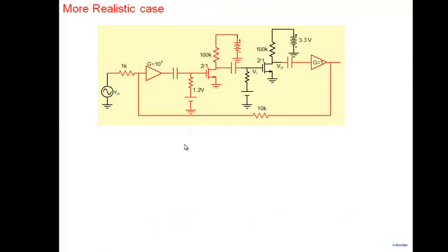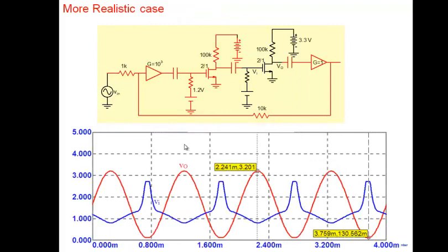So, these are more realistic cases. The message is, if I have a standalone amplifier, I have to worry about harmonic distortion, and the swing and all that we calculated is required. That's how you would design. But if you're going to take this amplifier and embed it in a feedback loop, then you go ahead and bias it in the middle, and that should be fine.